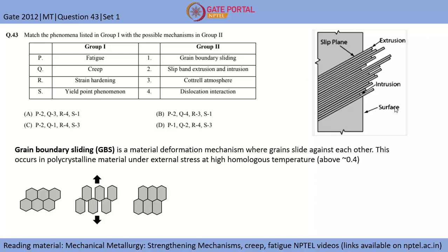Firstly, coming to fatigue. In fatigue, as you can see in this schematic, a slip starts in a particular grain which is oriented in a preferential manner with the loading axis. This is the basic cycle of fatigue. So there is some sigma max and there is some sigma mean.